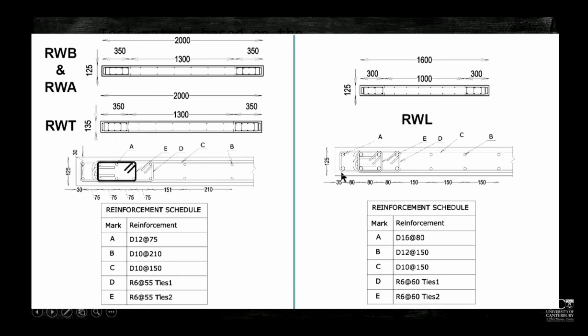So we decreased the length, increased the thickness, and for the specimen that had a reduced length, we increased the reinforcement ratio to compensate for the reduced lever arm and to provide the same flexural capacity as the other specimens.